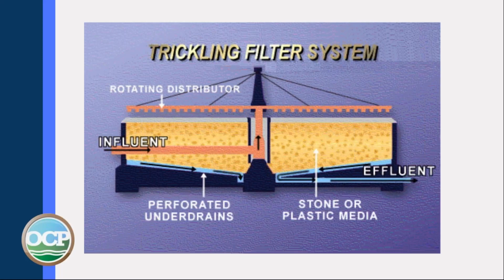As the water comes off of the media, it goes through the underdrain and onto your effluent. Also, any biofilm that builds up on the media, when it gets too heavy, will fall off, and it also goes out with the effluent into your secondary clarifier.